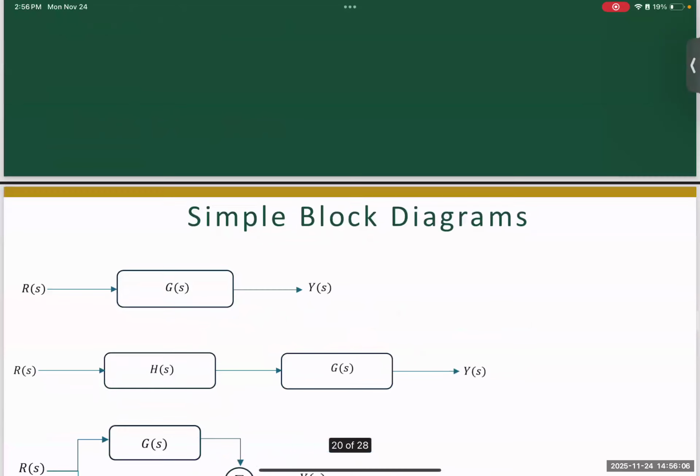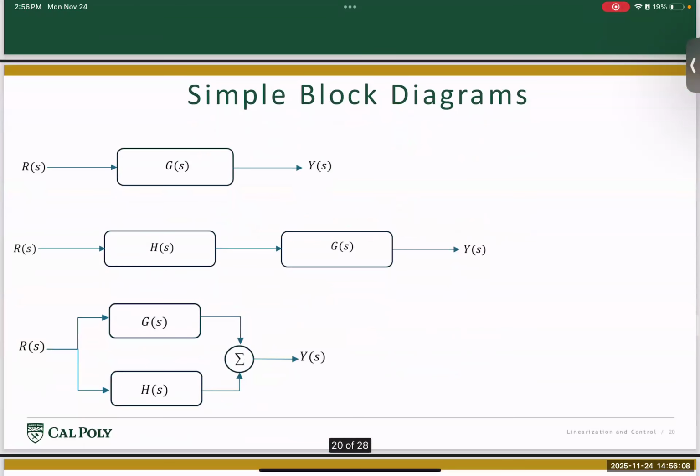Now, if you notice, typically when we were analyzing each of the behaviors of these systems, they're all dependent on time. And they're usually given as a set of differential equations that you need to solve for. One way we eliminated the need for solving these differential equations is we converted them into the Laplace domain, where now all the differential equation integration and differentiations got converted into algebraic quantities, where you're just performing multiplication, subtraction, addition instead of integrating equations or differentiating them with time.